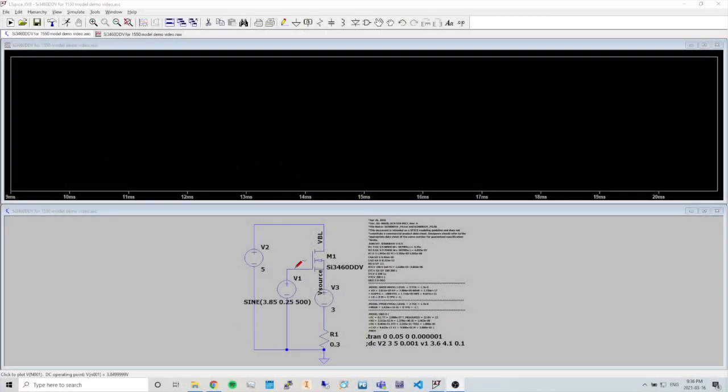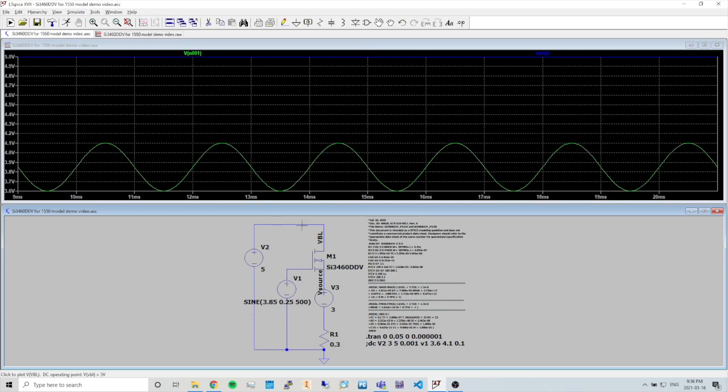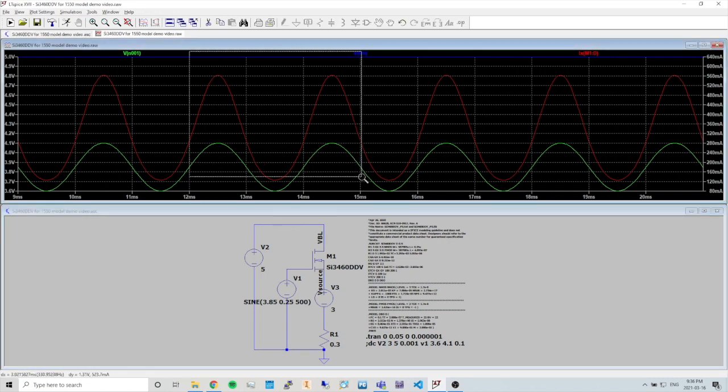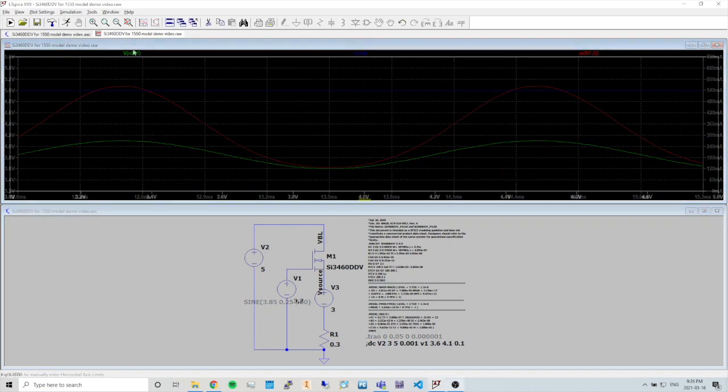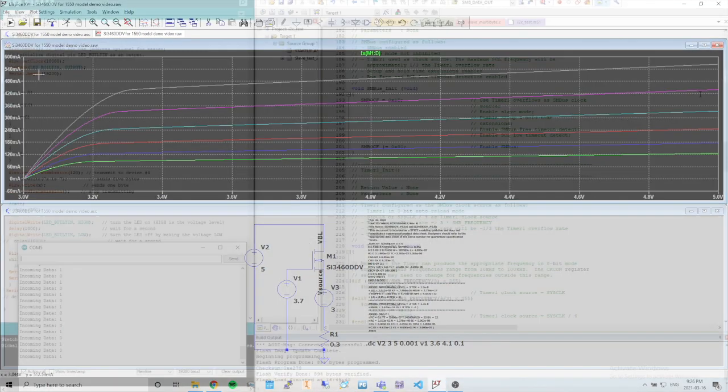The laser diode is a very sensitive piece of equipment and needs precise electronics to operate it. A laser driver is required to ensure the laser diode receives necessary voltage and current so that it operates at the required optical power. The laser driver must also ensure the laser diode safely starts up and shuts down.